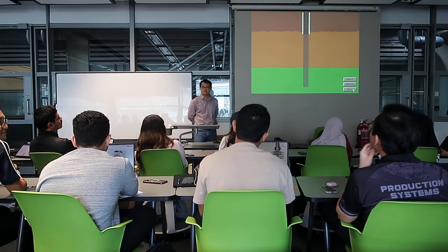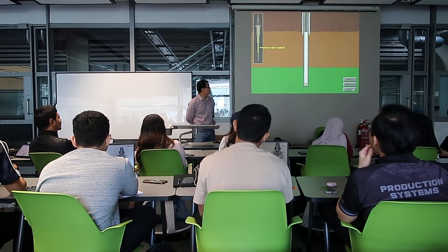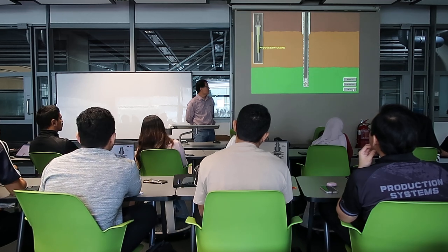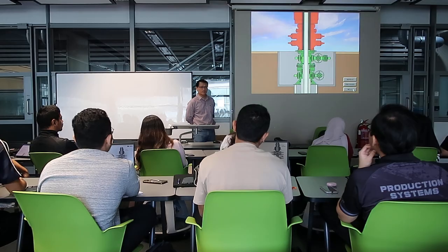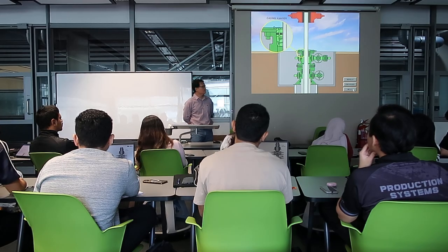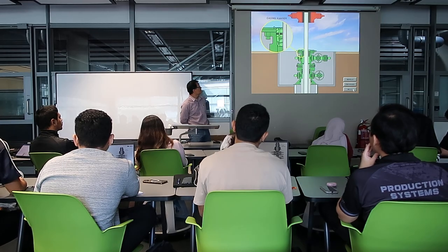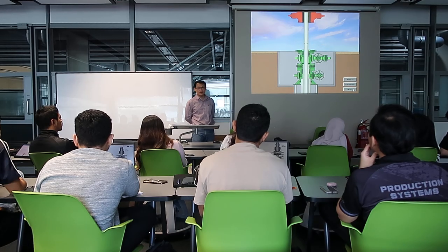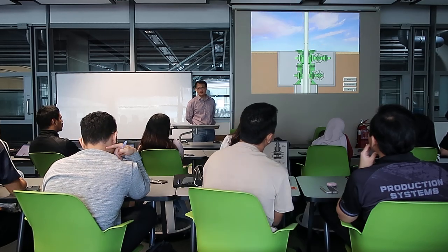The production casing string is generally run to the total depth of the well and is the casing string in which the production packer is installed. When the hole is drilled and the production casing is run and cemented in place, the casing hanger is installed. The casing riser is drained, a rough cut is made, and the BOP system removed.